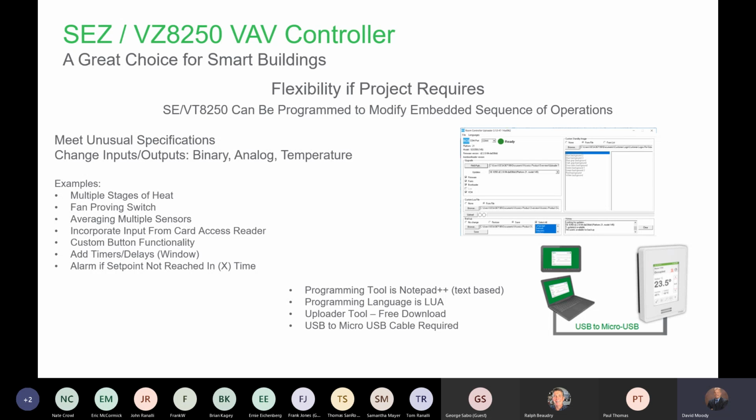So the point is you can take this 8250 room controller, and you can make it do pretty much anything that you want, besides the out of the box functionality that it has. You can get creative, and you can write programs to configure itself, change set points back at midnight to something else. These are just some things off the top of my head that people use.